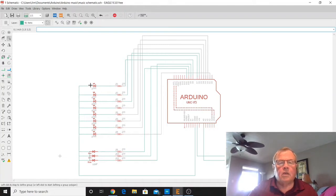Like always, the LEDs themselves have a polarity to them. The long lead of your LED is connected to the high voltage, the 5 volts coming in. The low voltage, which is tied to ground, is the short lead. So that's the polarity that you have to have on your LEDs.